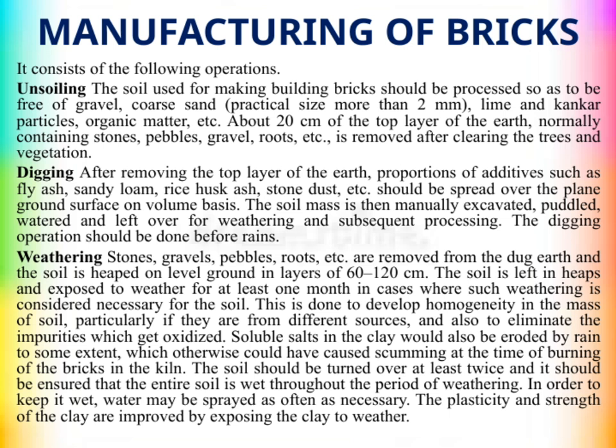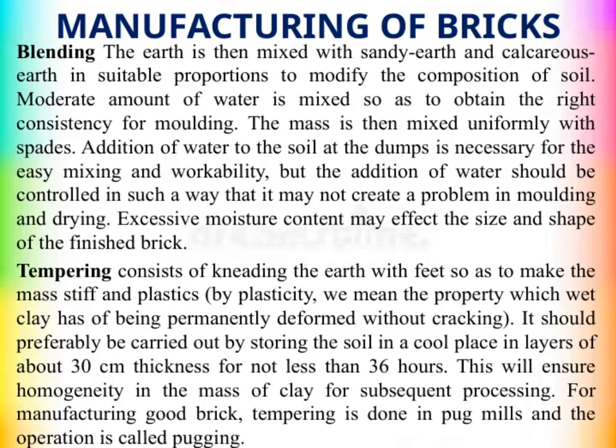So in summary, these steps, unsoiling, digging, and weathering, are fundamental to preparing high-quality soil for brick production, helping us achieve durable and well-formed bricks. Let's talk about blending, which is a crucial step in brick manufacturing.